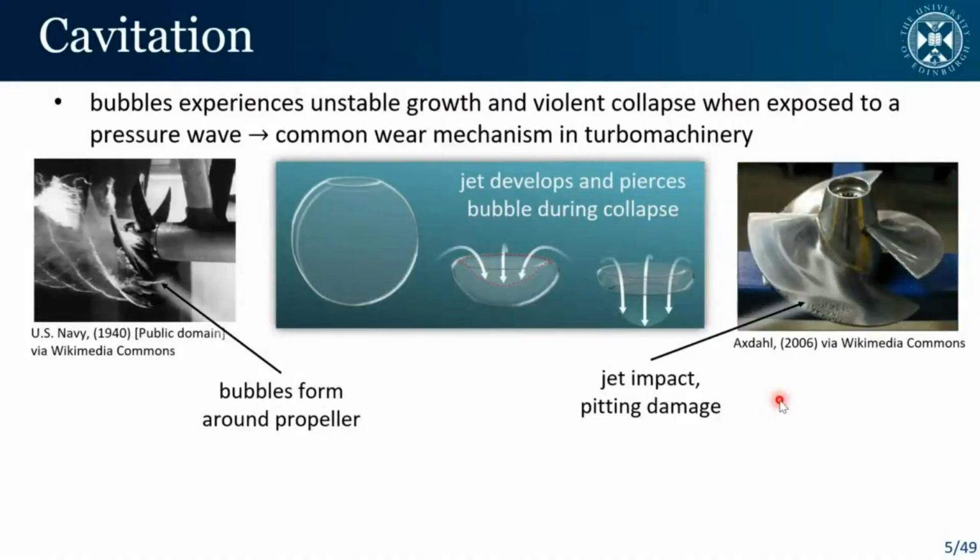If you think about boiling your kettle, that might take several minutes to reach a temperature of 100 degrees. But pressure can fluctuate many hundreds or thousands of times a second. Just me speaking to you creates fluctuations in pressure. We can also see this in turbomachinery, where cavitation is quite a significant problem. As a ship's propeller spins, you get large cyclic fluctuations in pressure.